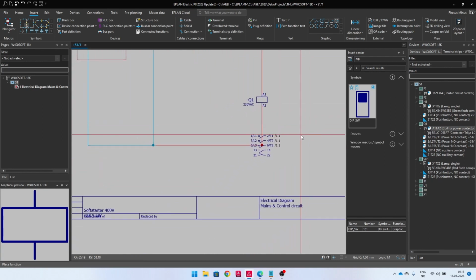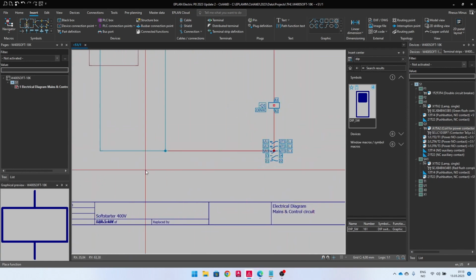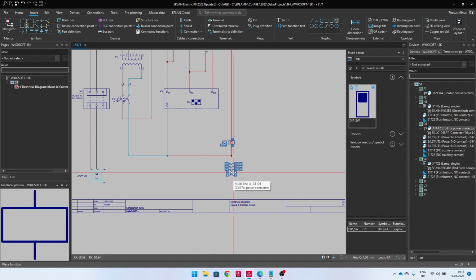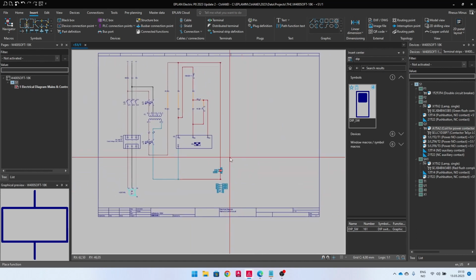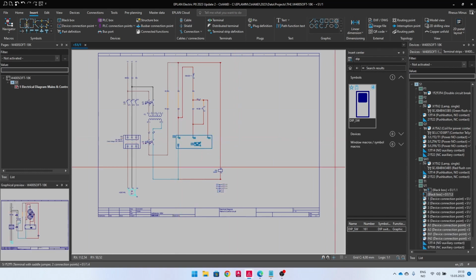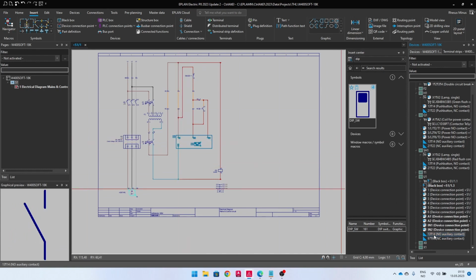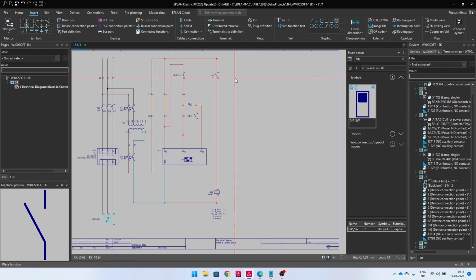Let's see that this predefined height for this one is a little bit tall, so I'll just move that up like this. You can set up for yourself what the distance should be from the bottom up to the top of this contact mirror. But I'll just keep that one. I want to get the 13/14 contact from Q1, so I will just find that in my list. I use the Ctrl+F button to find that in the navigator. So I can just drag it in like that and place it in my schematics.